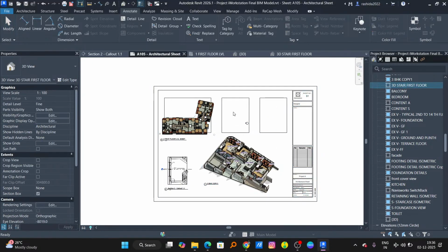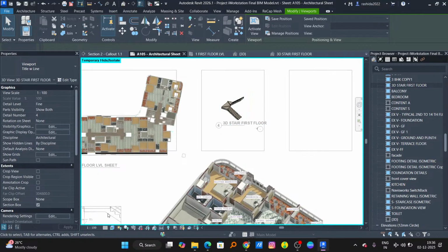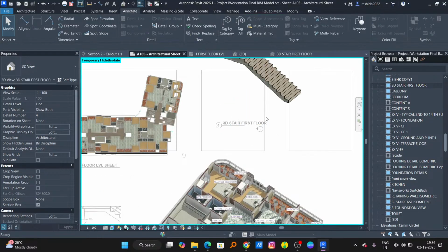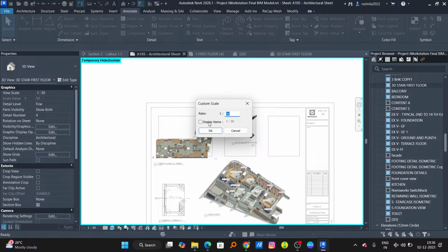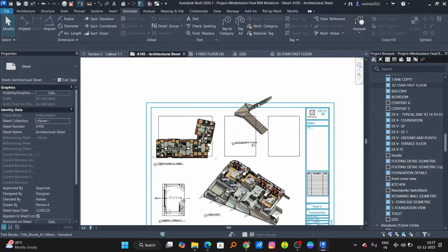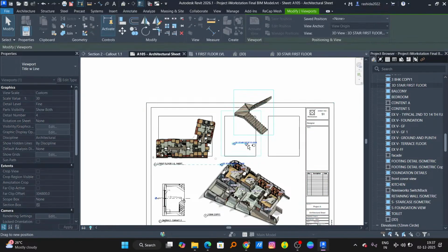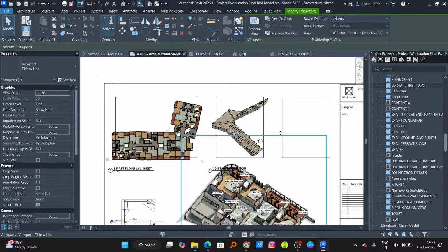I need to come out first. So here's the staircase. It's currently 1:100. Let's make it 1:25, or 1:50 is also fine. Too short. Why not go with something in the middle, like 1:25 or 1:50? Let's make it 1:30. You can make it custom also, 1:30. Okay, this looks fine. Yeah, custom scales you can also use. It's not necessary to always follow the default version of something.